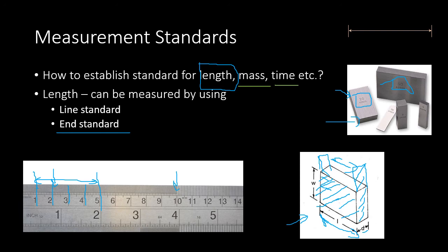Similarly, this slip gauge can be used to measure a distance of exactly 50 mm. That means if you want to measure 70 mm of distance, you need to combine those two slip gauges. We will talk about combining slip gauges later.